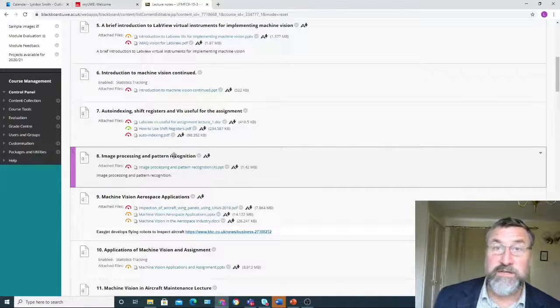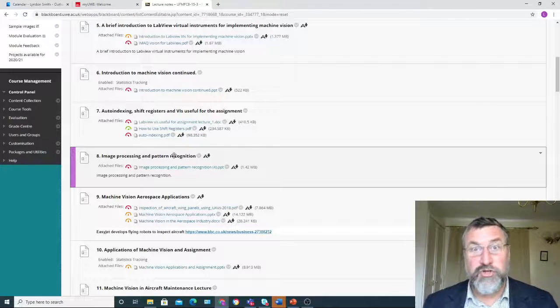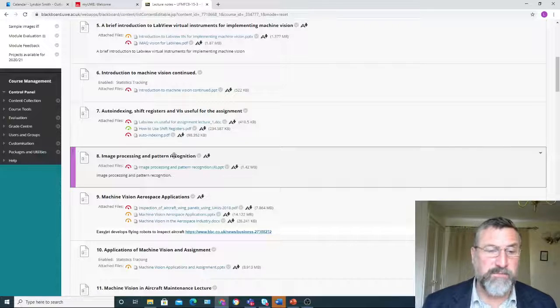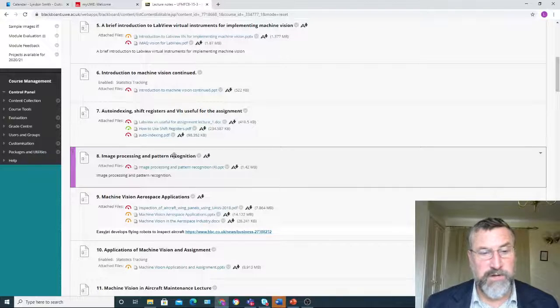And that's why lighting is so important, because that can help you highlight features of interest and thereby reduce the processing complexity of the program. You don't need so much cleverness in the program because you're getting more useful information immediately out of the image. So careful structure of the lighting can really help you in setting up a good machine vision application.